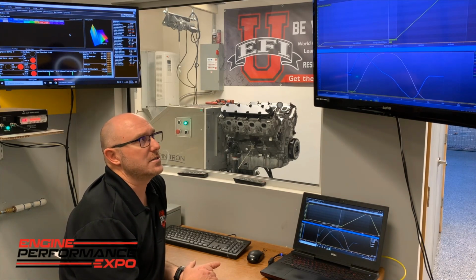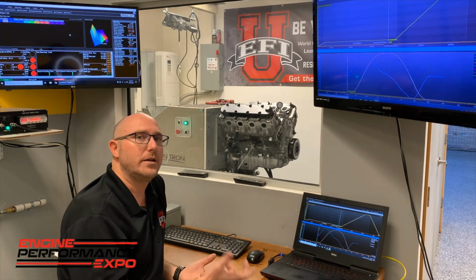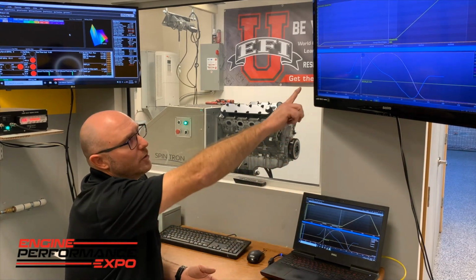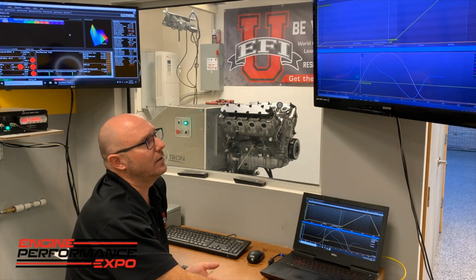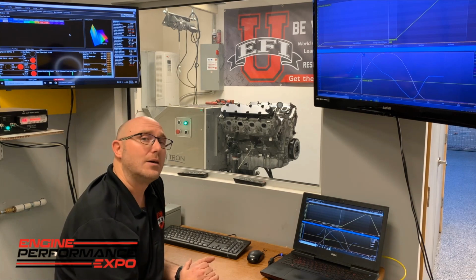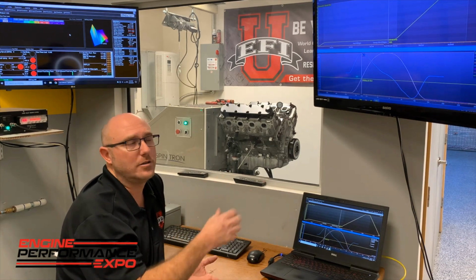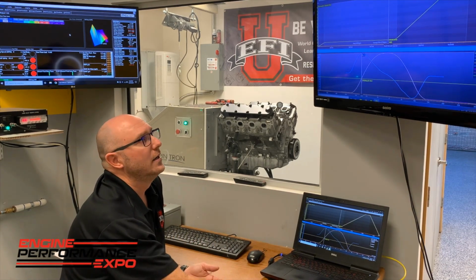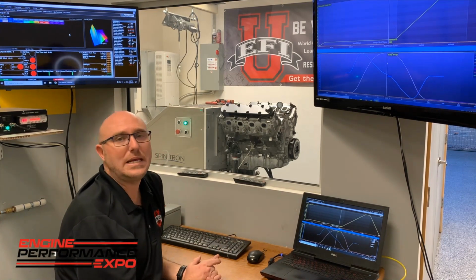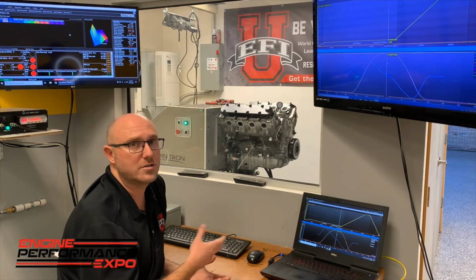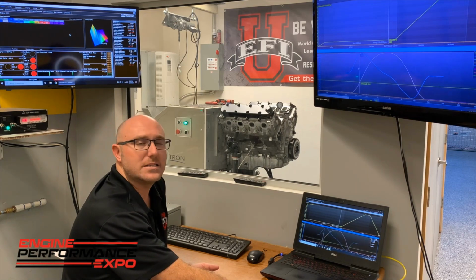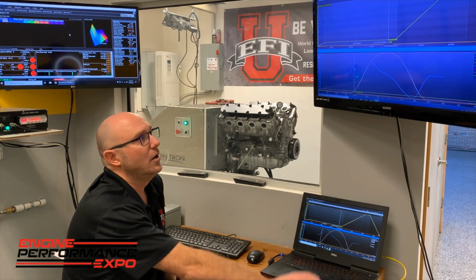So in this case, the velocity is how much lift we're getting per degree of crankshaft rotation. And we can look in here and see that it maximizes here about a third of the way up the opening ramp at somewhere around 7 1/4, 7 1/3, 7.3 thousandths of an inch for every degree of crank rotation is how fast we're accelerating there. Then you can see as we go over the nose, we're basically zero. Our speed is zero because we're not going faster or slower. And then, of course, it starts to go negative until we get back on the seat. So we can look at the velocity as the derivative of position on the lobe.